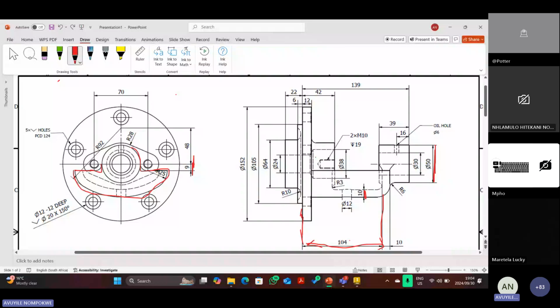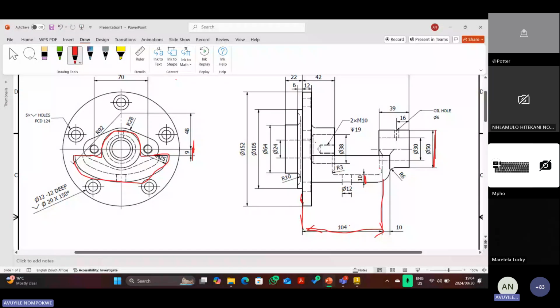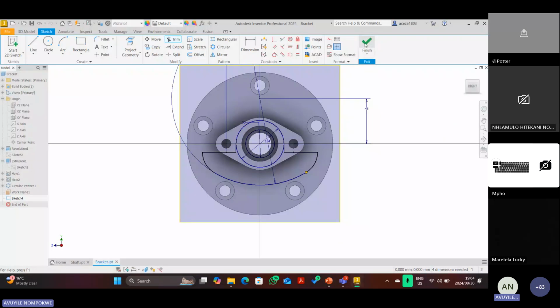Looking like this. All right, so now we're going to extrude, okay? And then we know that this thickness is 10, right? So here it's 10. And then we know that we are drawing our sketch here because remember we offset the plane by 104 millimeters from here to there. So meaning that we have to extrude going to that direction. Okay, let's come here now. We finish. Wait guys, are we done? We're not, guys.